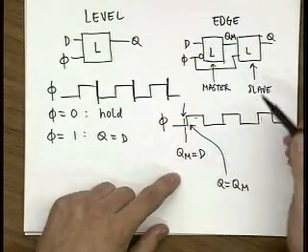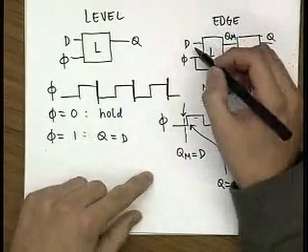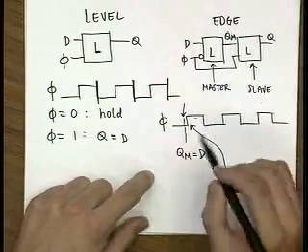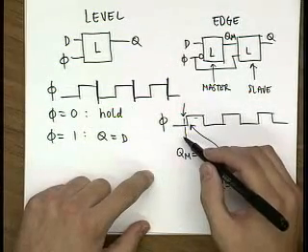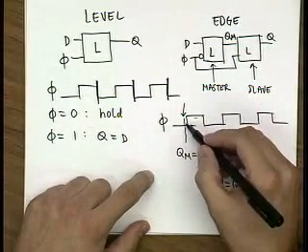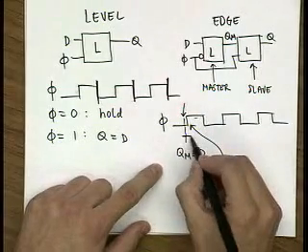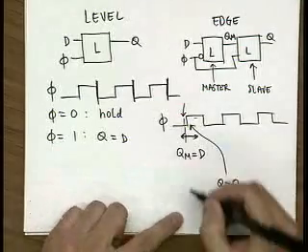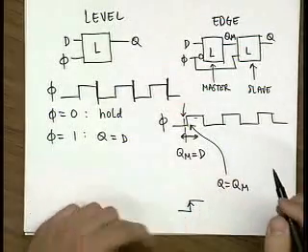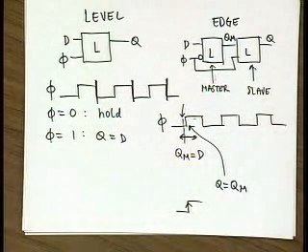So that means that looking back now one more stage backwards, your data, the last chance you can change your data before you capture it at the final output is the hold time before this latch closes. So you have this very narrow sampling window here that actually appears as if you are edge triggered. So that's basically two things that you need to remember.